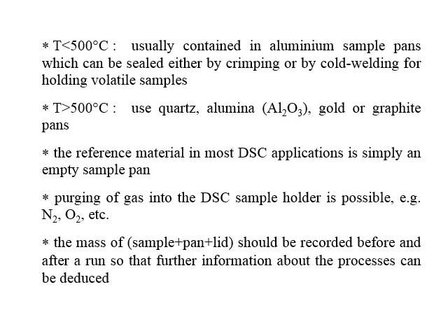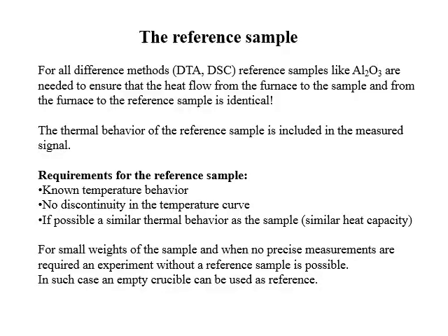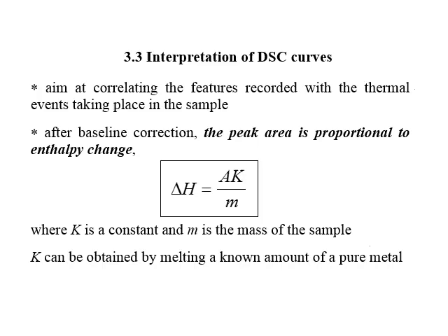You always do want to understand the mass of the sample, the pan, and the lid before and after you do a run so that additional information can be used. Plus, understanding the sample mass before it goes in allows you to do things like calculate specific heats and so forth. This slide appears to basically have the same information that we talked about in the previous slide, that the reference sample should basically be similar to the sample itself, so you can read this slide on your own.